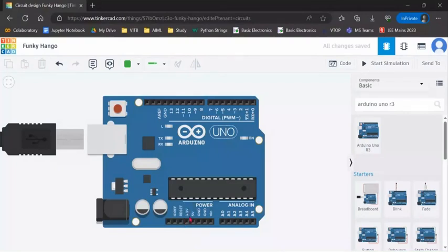3.3, if we connect it to this terminal, it will be providing 3.3 volt. Similarly, this will be providing 5 volt. This is ground. This is another ground. This is V input. If you want to put the input here to the microcontroller, we can provide the input from here. This is for input output reference. Basically, this is reserved or unused. It can be used for further processing. So this is the basics about the Arduino Uno.